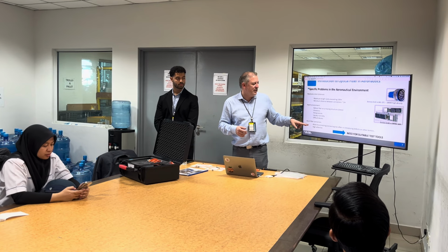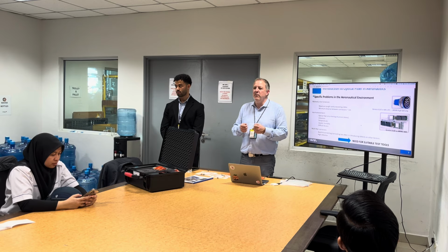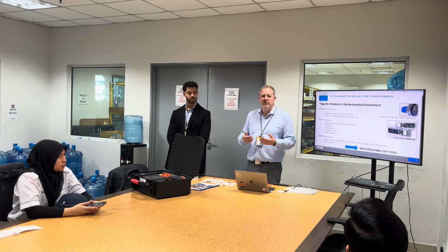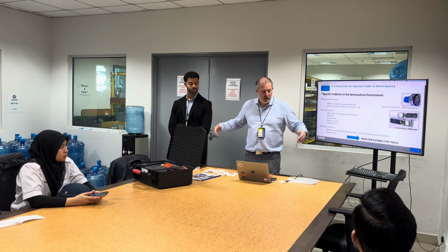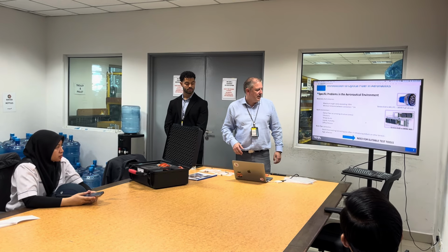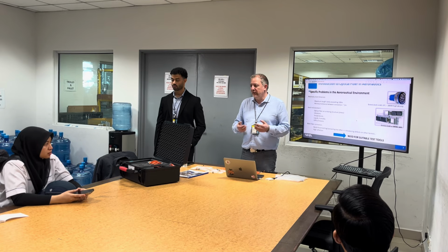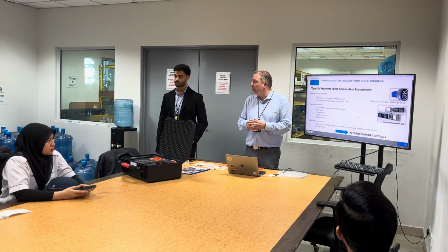One recommendation is the less you disconnect and reconnect fiber optics, the better, because each time you disconnect and reconnect, you may stress the connector, you may have some dust inside, so that may affect the global performance of the full transmission. So be careful not to induce other faults on other connectors. Be very careful when you manipulate fiber optic connectors.